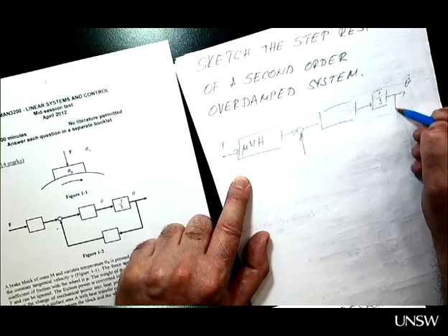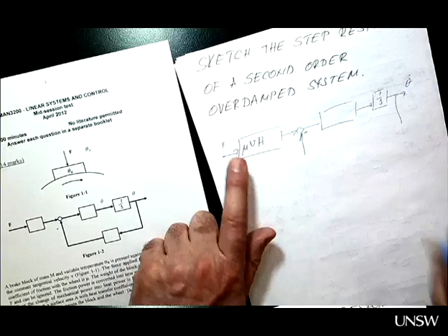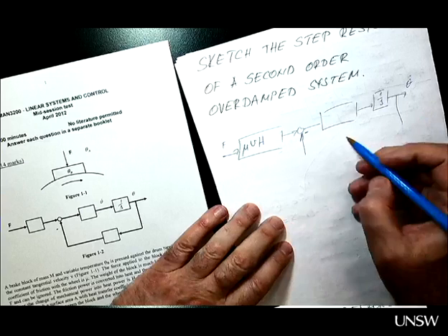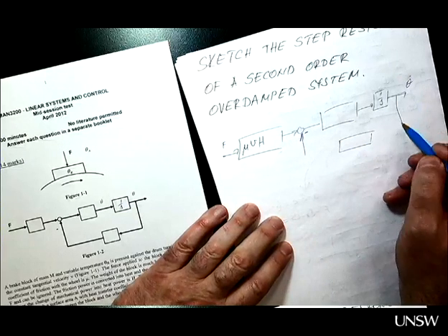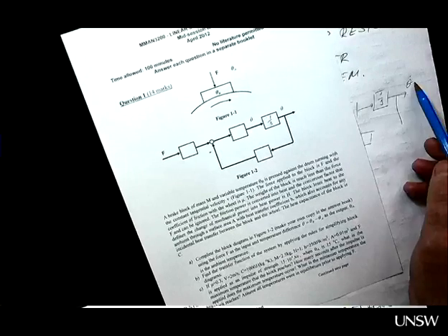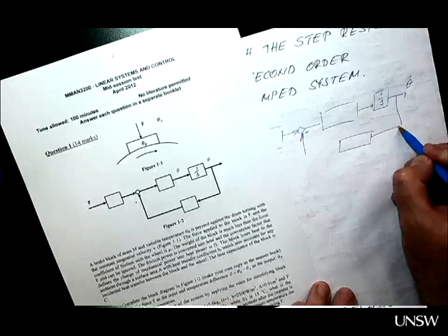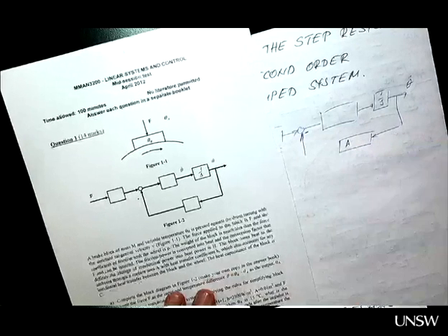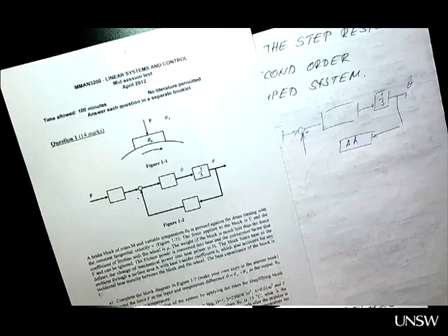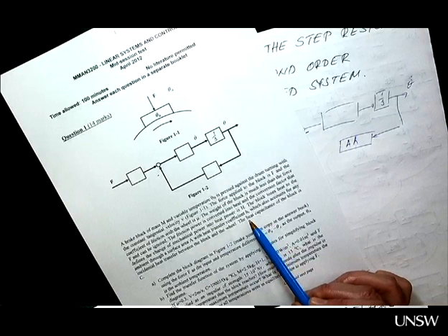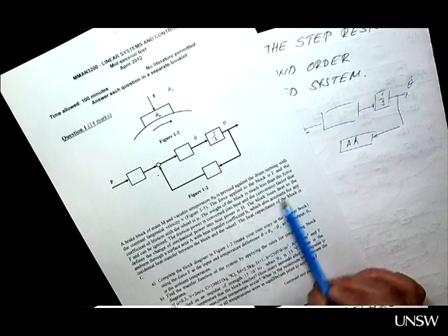So what takes the heat out of the block is the heat released from the block into the atmosphere. That's what cools the block. So heat released into the atmosphere will depend, just one more point here, theta is actually the difference between the temperature of the block and the temperature of the ambient. So it is theta times A, which is the area of the block, and small h, which is the coefficient of heat transfer. How did we call it? Yeah, heat transfer coefficient h. So the block loses heat to the ambient through surface A with heat transfer coefficient h.